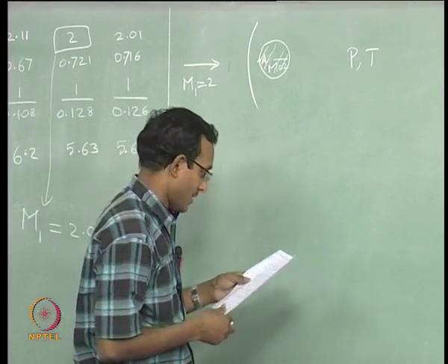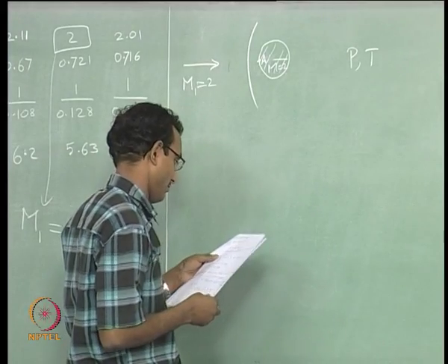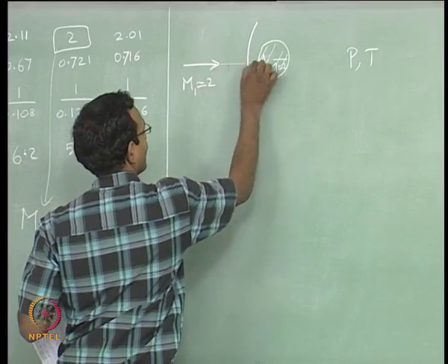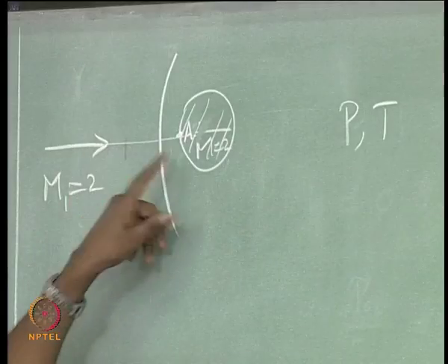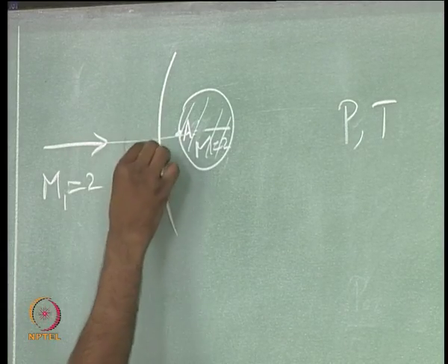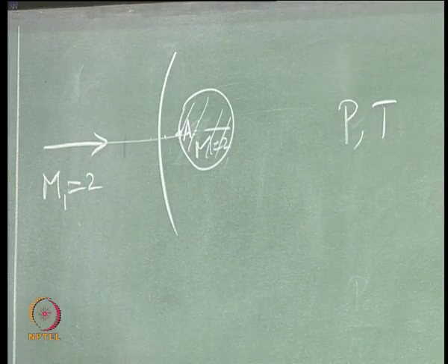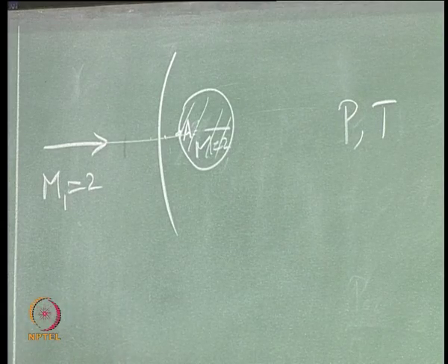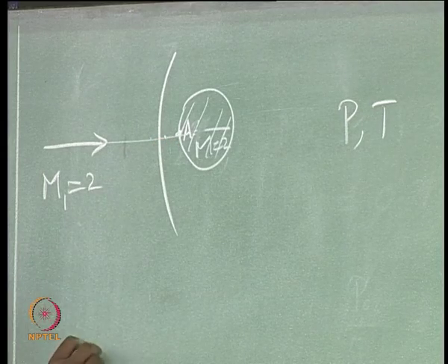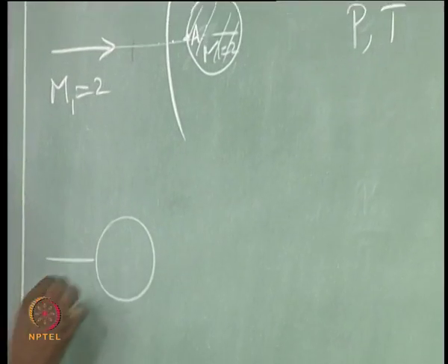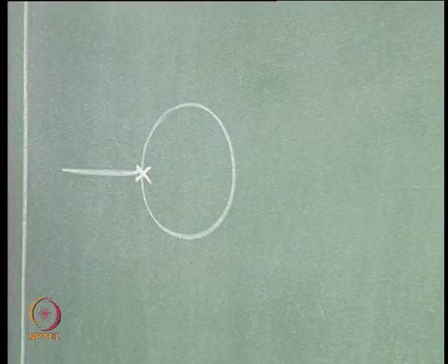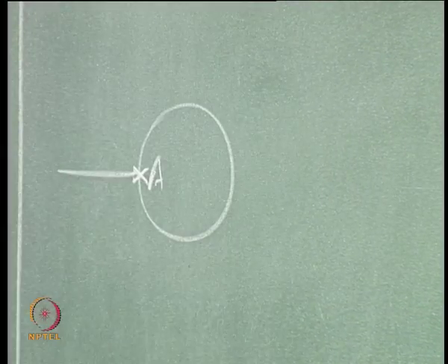If I am trying to find that, it is a simple enough problem. Of course I have to first cross the shock. The streamline that is going straight there will be the streamline that is going to cause the pressure there. So across the shock, of course P naught drops, but T naught stays constant, Mach number drops. After that the flow is subsonic. Now if I look at subsonic flow around a cylinder, it will achieve stagnation pressure at the frontmost point, which is what we are interested in this problem.